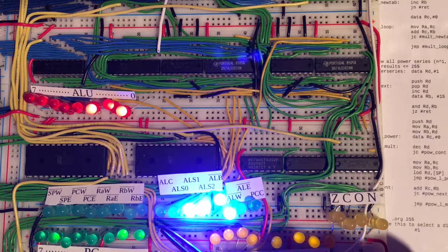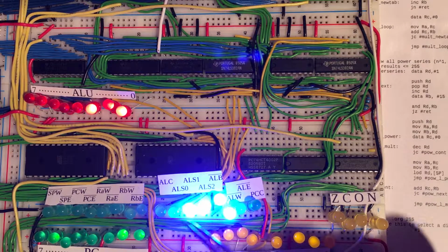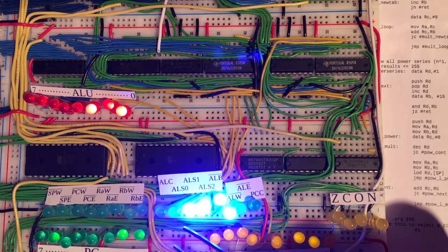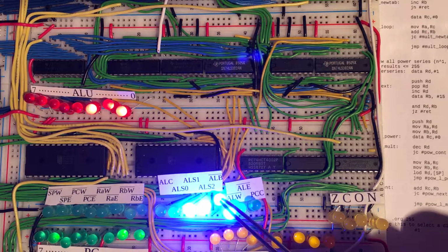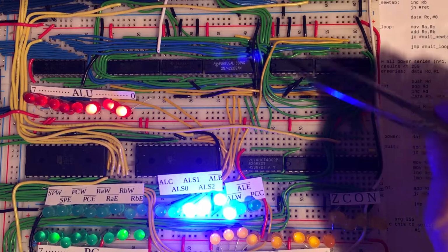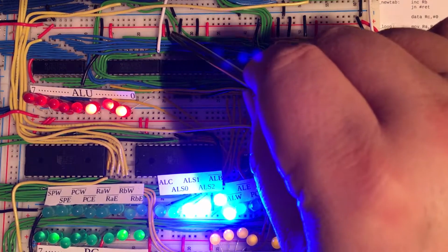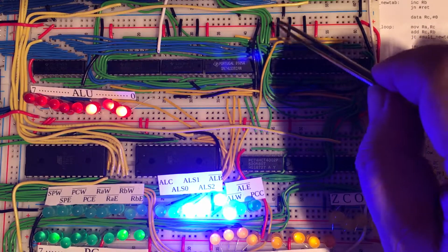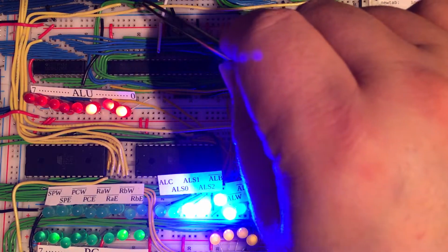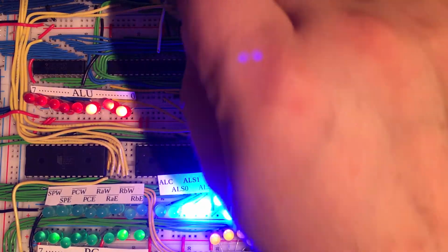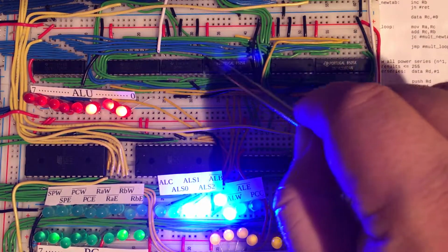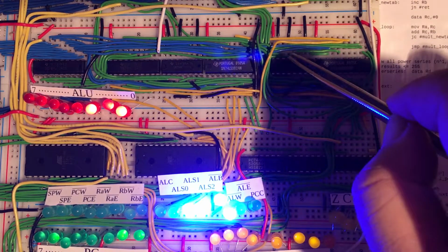And so for this operation, we can see that these first 4 bits, which send the actual operation code to the ALU, are different. They are 0, 0, 1, 1 right now. But the interesting part is, for this instruction, we're telling the ALU that its second operand should come from the B register. And in fact, if you look very closely, you'll see 4 green wires here moving up from the ALU. And here are the last 4, so that's 8 wires in total. And they're actually hooked up to the B register. So the output of the B register is always available for the ALU. So that's not coming to the ALU through the bus, that's directly wired to the ALU.